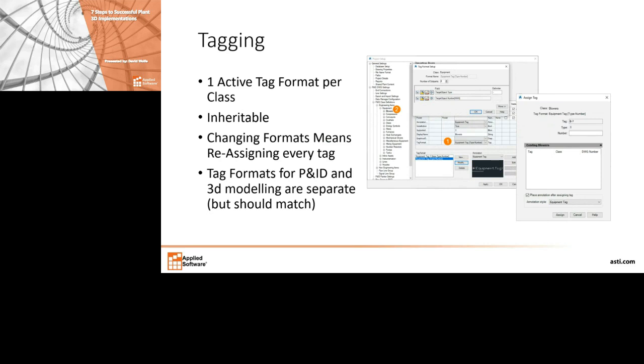But just keep in mind that if you went to retag something like an old thing, if you hit the assign tag dialog box and you hit OK, it would update with whatever is current. And so you might lose an old tag and have to go back and fix that. Also, you're not going to get any conflict checks. For example, it's not going to check if the tag format's not current. It's not going to check the area property to make sure that it's in the tag. It's just going to check the string that's there.